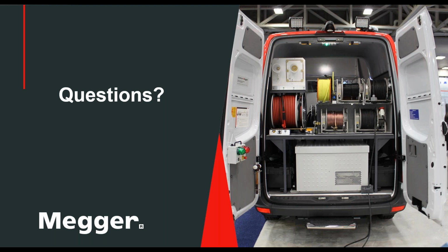Okay, so as stated before, branches require the ability to isolate from some middle point of that said branch. But if you cannot isolate from that branch, what we say is you can try from each end. And if the fault is close enough to your hookup point, meaning let's just say it's a 4 branch, 5 branch, however many branches you decide. And if you cannot isolate from one middle point and look in each direction, you could try from each end. If the fault is close enough to your hookup point, the radar/arc reflection might give you a good enough trace to give you footage, but depends, as stated before, on how close the fault is to your connection point.